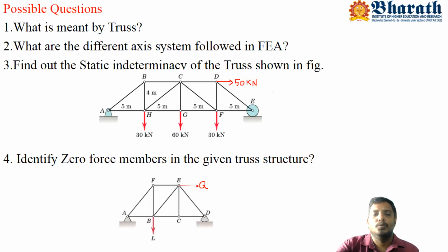So once you have learned this lecture, we can address these possible questions. The first question is: what is meant by truss? A truss is nothing but a group of structural members joined and welded together to carry only axial stress. The load acts only at the joints. All the members in the connected truss element are pin joints. It carries only axial force.